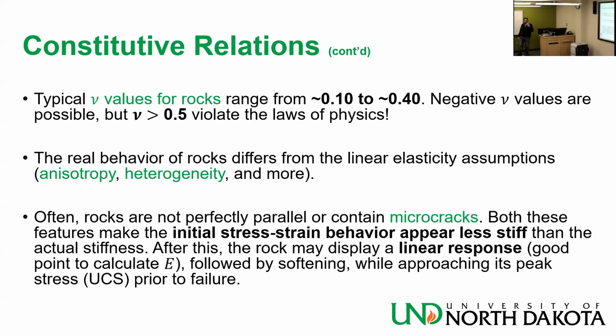So initially I apply a small stress, I get very big strain for the stress I'm applying, because there are microcracks that are closing down. So the material is not fully solid. It's solid with some defects.